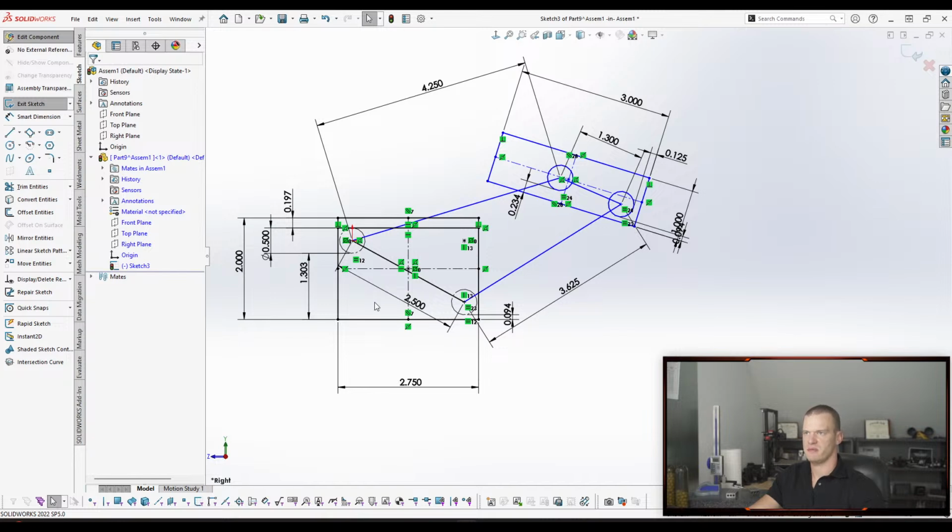It's less likely to fail, because sometimes you'll get in a situation where the solve order in SolidWorks will mess you up, and you have to hit rebuild to get your parts to solve properly. The sketch relations seem to be a lot more robust, reducing those errors, rather than using dimensions to define everything. So yeah, I think that would be my two biggest pieces of advice.